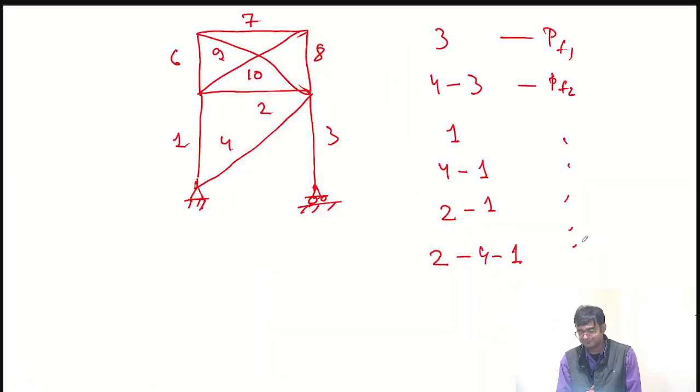So in fault tree, you find different ways the system can fail. In the other one, which is safety based, you analyze different ways the system can survive. And in that case, it will be a union. In this case, it will be an intersection. I mean, in this case, it is a union. Like if one fails, everything else will fail. In that case, all those survival has to be there. So you will calculate the probability of survival, and that will actually overestimate. So that is a safer one. But that is generally preferred for brittle. This is for ductile.